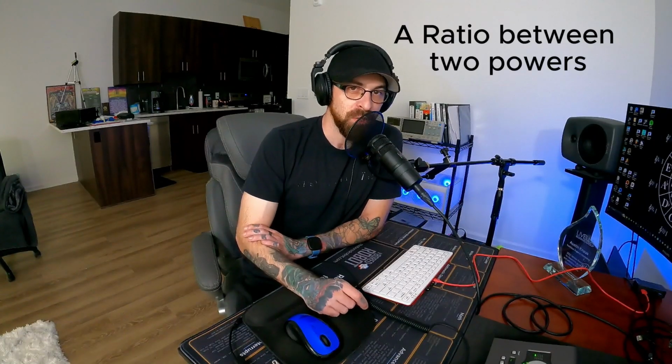A better definition of the decibel is a ratio between two powers. Whether it's in voltage or in air pressure, the dB is still a logarithmic equation. So the dBV and the dBu both measure voltage. So why do we have two different measurements that measure the same thing?